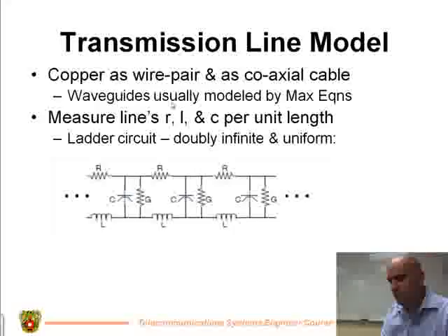Once you get up into microwave frequencies, you can use a waveguide, which is essentially wireless because it's going through the empty space in the middle of the waveguide, but it's guided like a wired transmission. So it's kind of a hybrid of wired and wireless. It doesn't attenuate like wireless does. It attenuates like wired, but it transmits through the air in the middle of the waveguide. So it's kind of a weird thing, and you pretty much have to use Maxwell's equations.